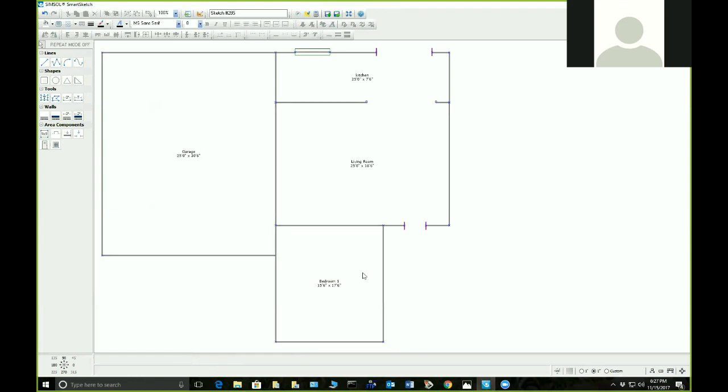All I need to do is use that snap point, and then it puts it into place. So it makes it nice and easy to do. If I need to add my door for the garage door opening, I can select it, and I can easily come up and say it's 16 foot and click apply. I can then move it over. So that's kind of the easy way of making up a diagram. This is just using the standard components, okay?